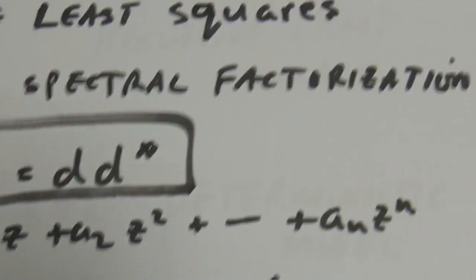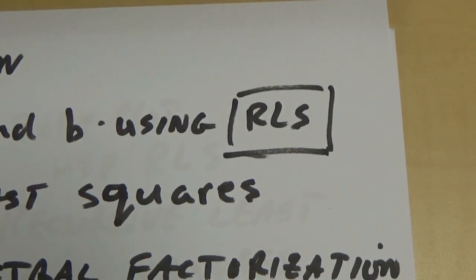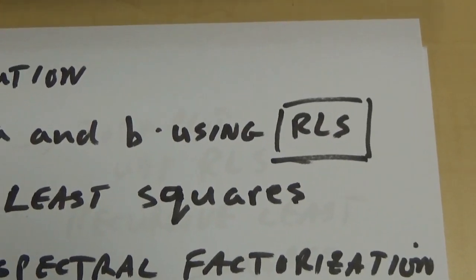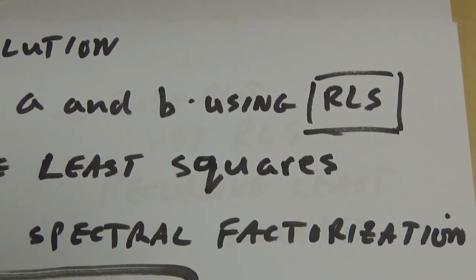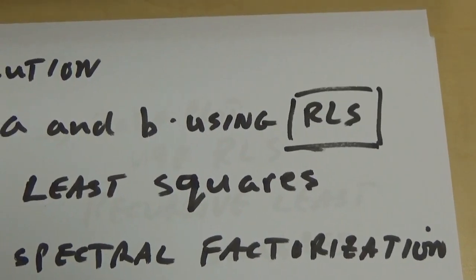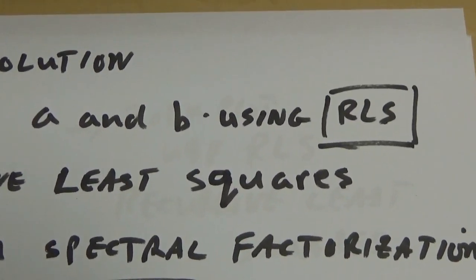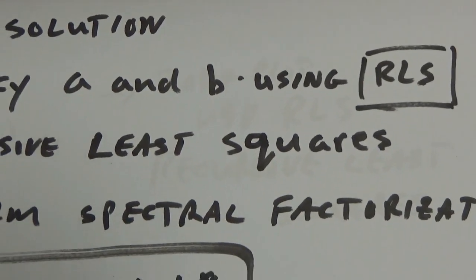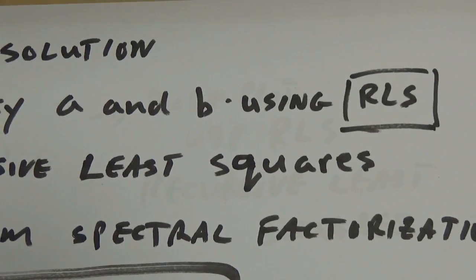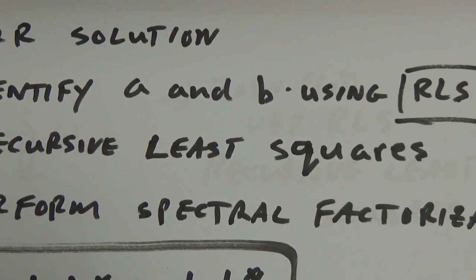What we won't be doing in real time is the recursive least squares. It's just a little bit too much. The other thing is, because the dynamics of the motor doesn't change with time, it's a fixed system, there's no need to keep continuously identifying the system over and over again. It's a waste. You only need to do that with systems that change with time.